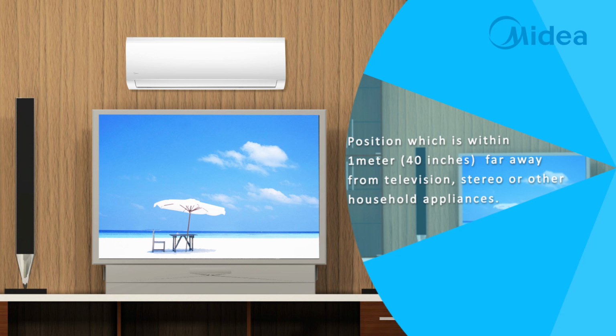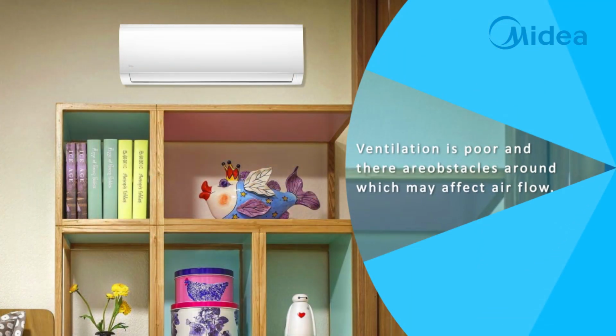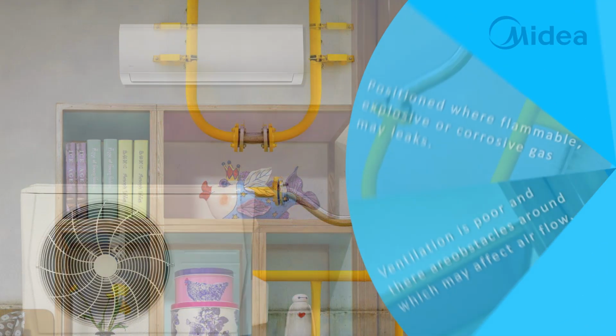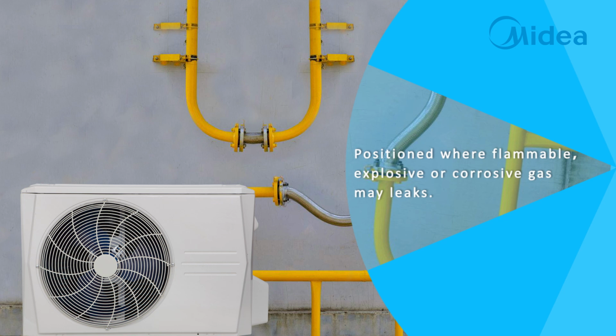Position which is within 1 meter, 40 inches, far away from television, stereo, or other household appliances. Ventilation is poor and there are obstacles around, which may affect airflow. Position where flammable, explosive, or corrosive gas may leak.